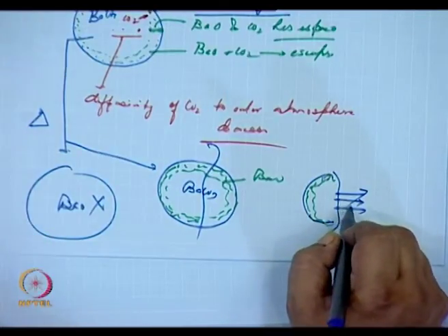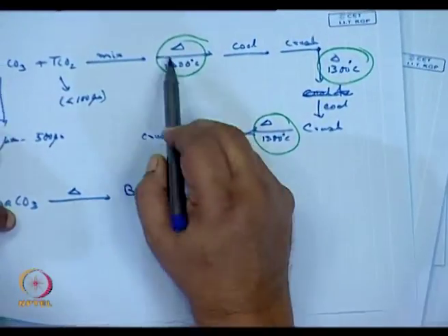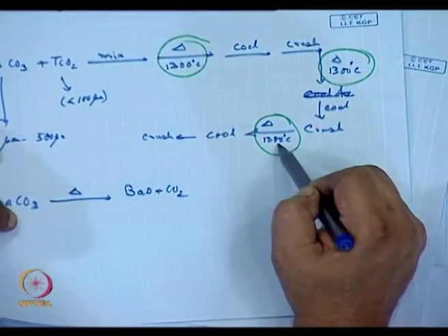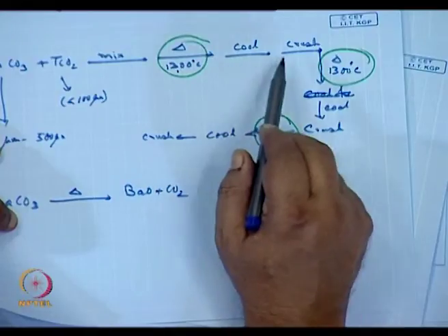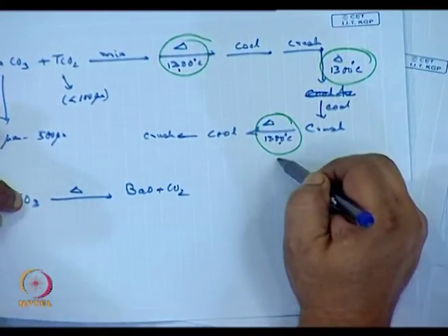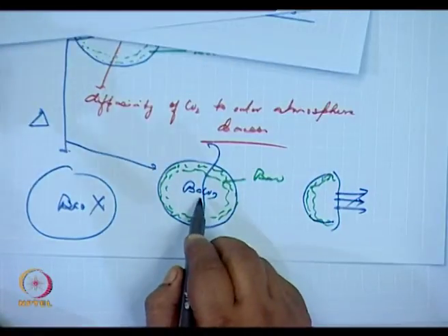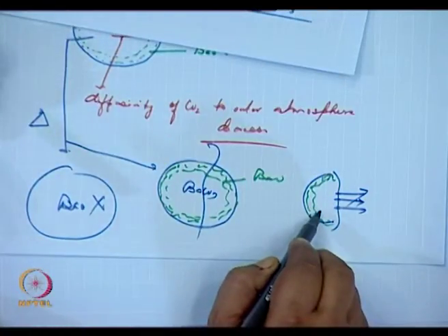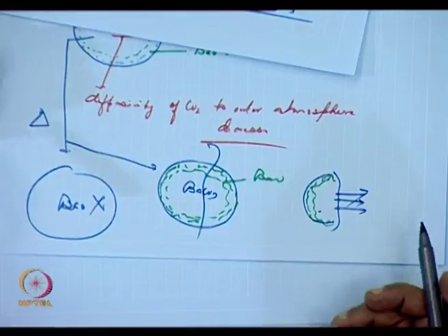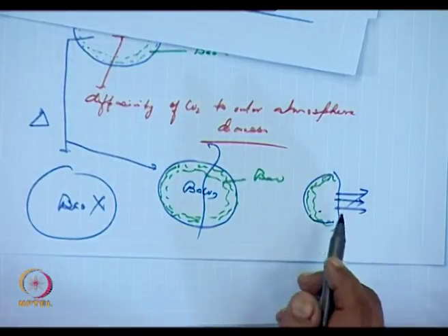That is one reason why this repetitive process of heating, cooling, crushing was done. In those two steps, the grains were being broken up to expose fresh surface, so that the BaCO3 could effectively dissociate and the grain was converted to BaO.